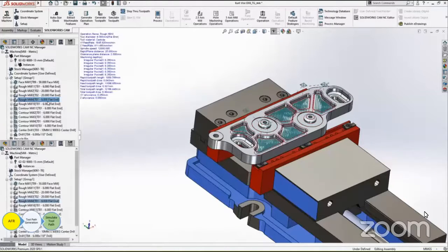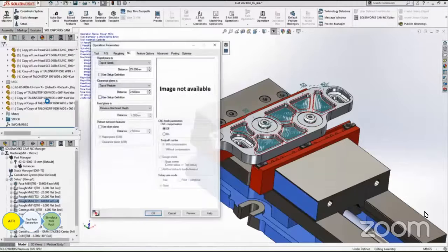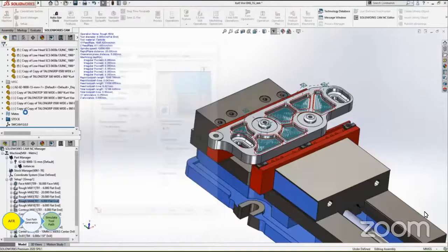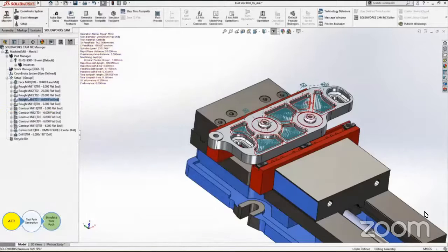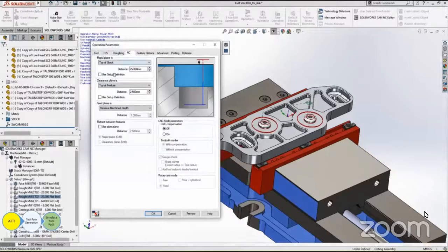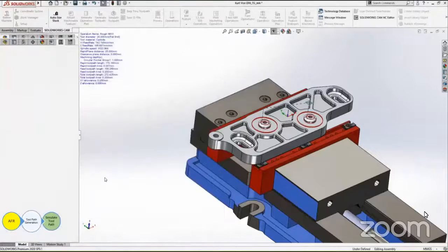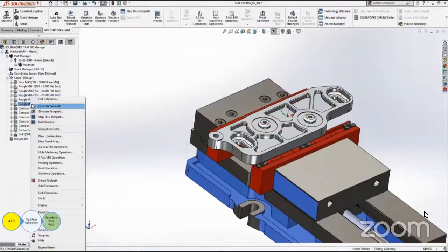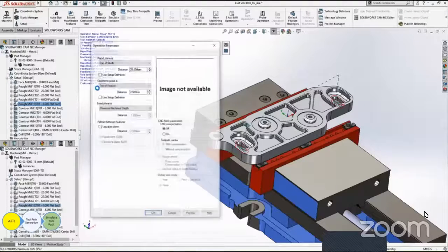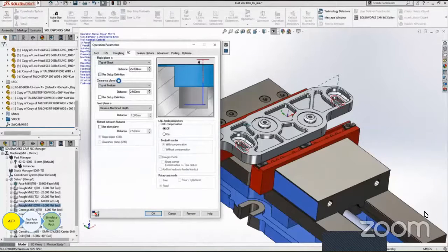So we have to apply this information to all of the roughing operations, so none of the tools should collide with the material while performing machining. Another way is, instead of using these safety precautions for all operations, we can identify which specific operation is in collision with the material, and then only select the settings for that specific operation.